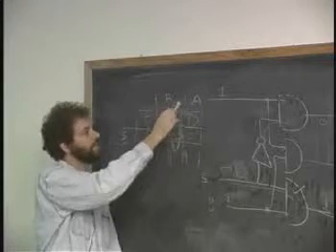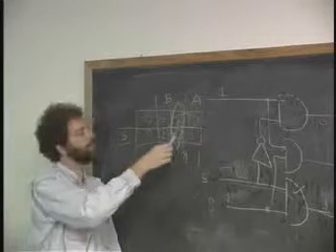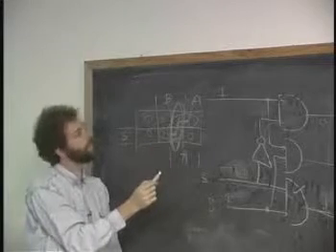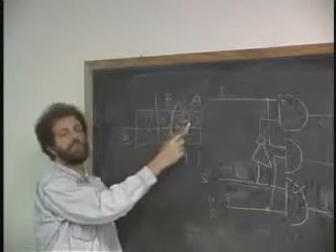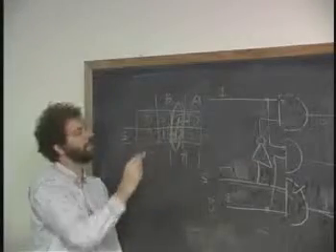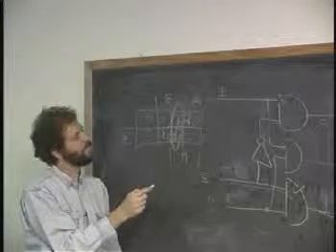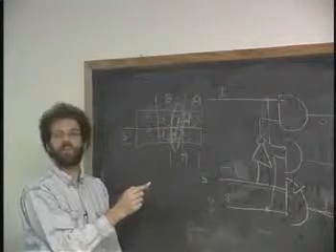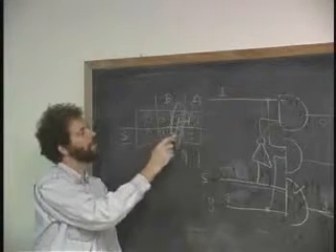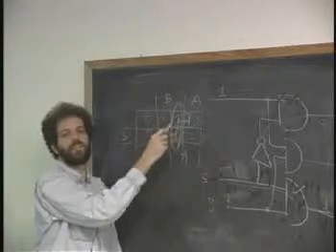That's what it means to have a circle that has more than one 1 in it. It means that we're eliminating inputs from the product term. Then when I go across this boundary, same deal, except that I have a circuit that doesn't care about B. It's A and S bar, this one up here. It is intuitively obvious that I cannot get a 1-1 hazard as long as there is a continuous path of stepping stones of these islands such that I never have to leave one before I enter the next one.